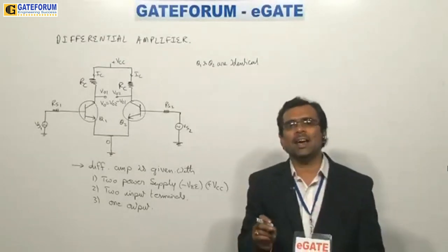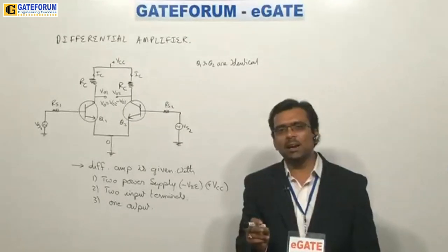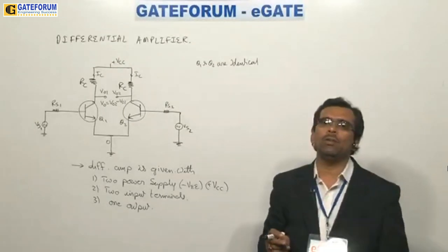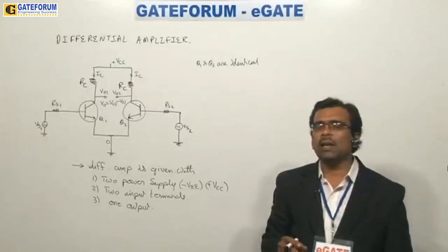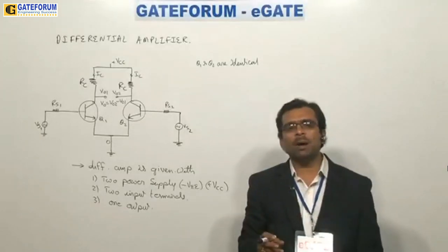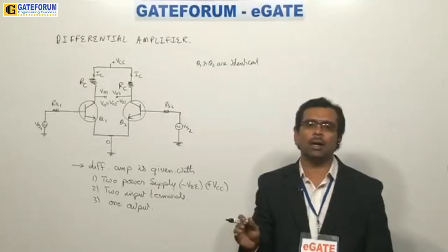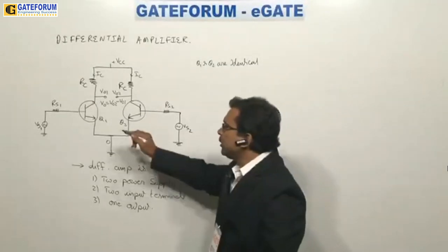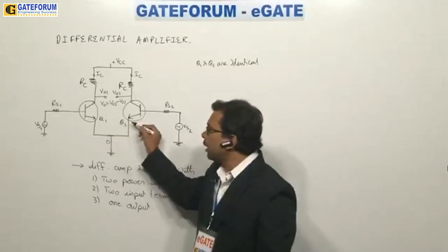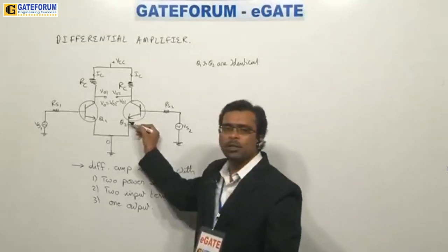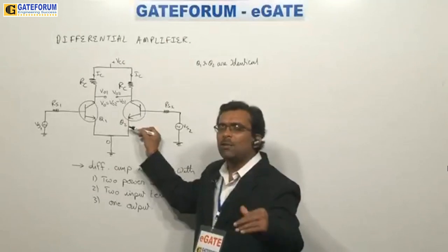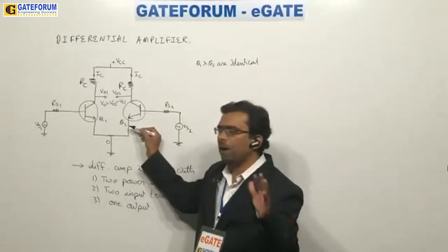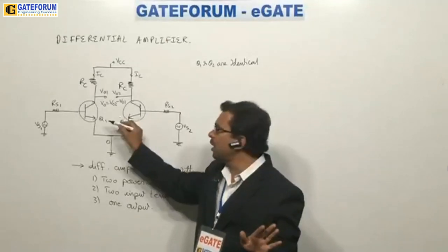In spite of taking care for this design, some variations will occur in manufacturing. At that time only we get offset errors. If there are no variations, or identical manufacturing is done, there is no problem at all. You can comfortably use this IC. However you try to take care, some errors occur because of mismatch in the transistors. That only we try to overcome externally using the offset pin. That is about the correction if they are there.